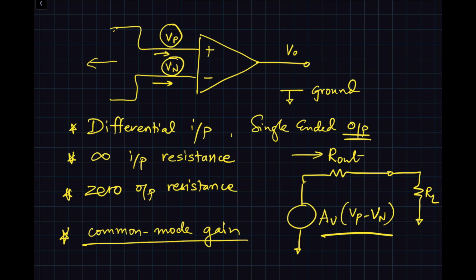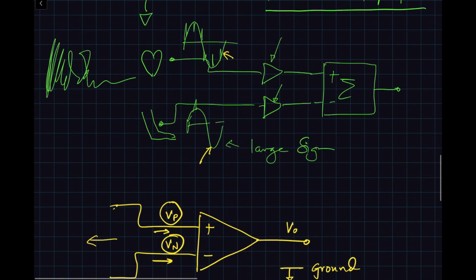So for example, in our previous example case, we were applying to this amplifier the common mode, like an AC signal, which is due to our power supply or electrical transmissions, which is 50 hertz, let's say, and that would be really large. And that would be the same on both sides, right?